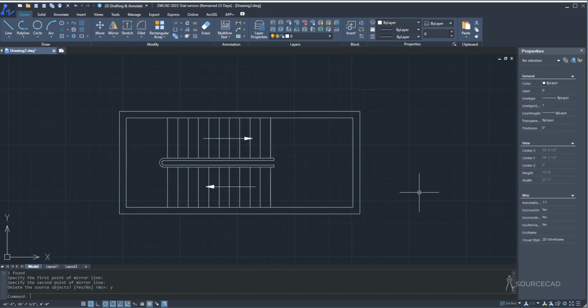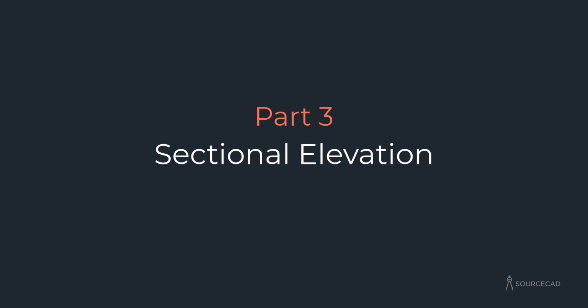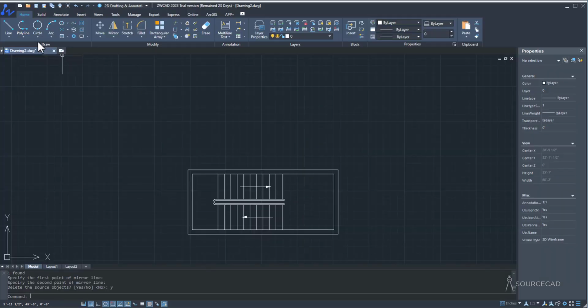plan view. Now using this plan view will make the elevation, the sectional elevation to be precise, and for that I'm going to add, well, some construction geometry. So I'll go to line, and here I have ray that I'll use, and I'll just track these points.